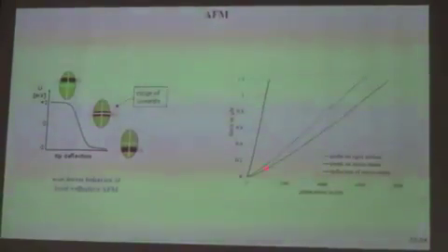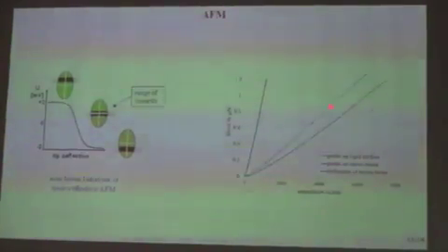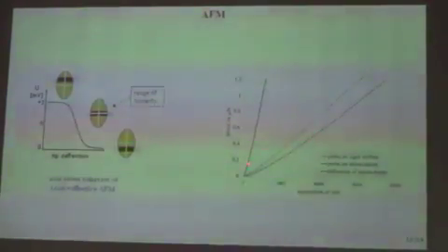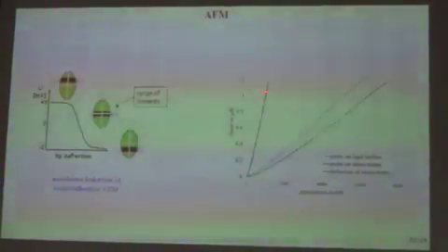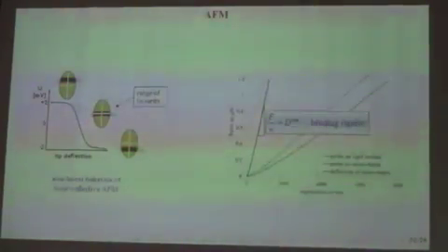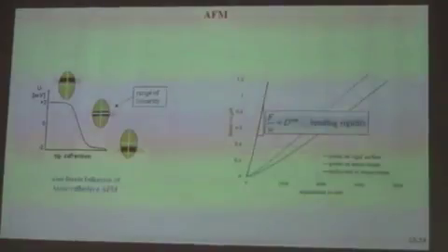And if we test now a rigid surface, this will be the blue line here, and then after this we test the microstructure, it is not very hard to see that the difference at every point here will be due to the bending of the microstructure. And this is exactly the information we need to build an experimentally derived bending rigidity.